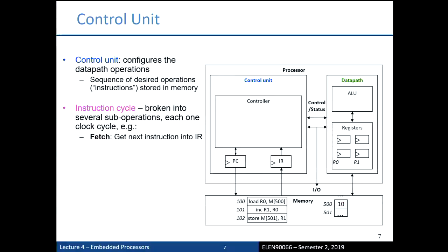So here's a piece of memory, and you'll notice that these are memory locations here. They could be in hex, whatever. You see that there's programs stored in there. This is assembler, pseudo-assembler, and over here is actual data. The memory is shared. There's instructions in one subspace of the memory, and then there's also data that's used as well. And what this micro does is it uses the program counter to go and fetch the next instruction.